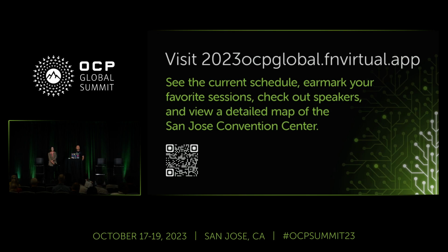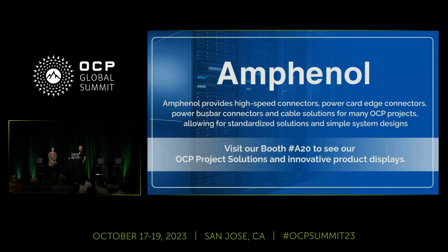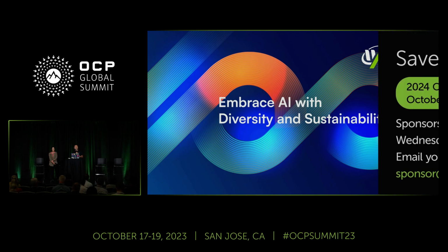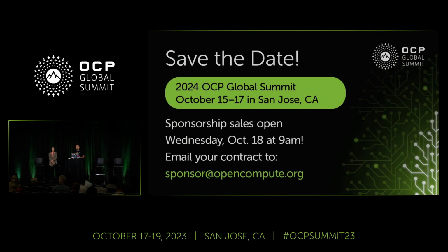That's a very good question. Traditionally there is a lot of discussion about correlation between TDECQ and the BER, even for the retimed module. We all know it's probably not the best correlation through all the corner cases.